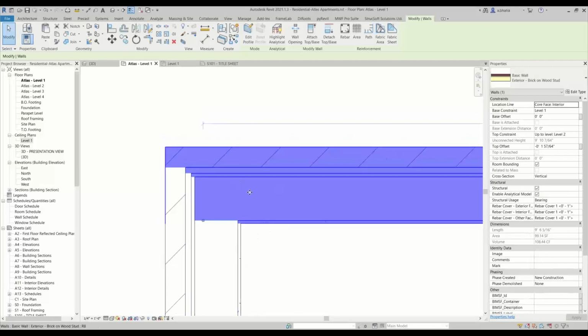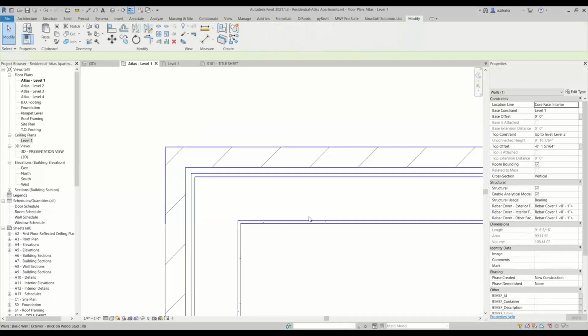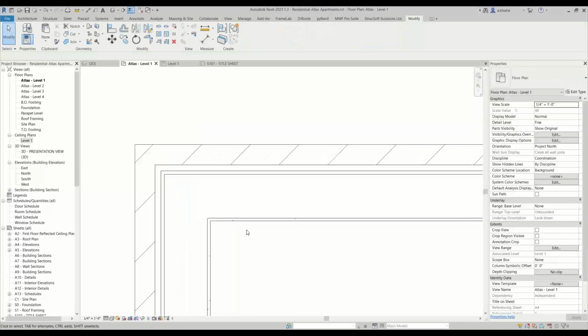Maybe you're doing prefab and this is one panel and this is another. So how do I make sure that when I'm creating a multi-layer panel and adding gypsum wallboard here and sheathing there, the elements extend properly?